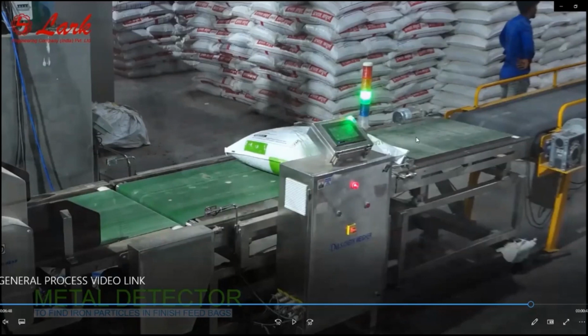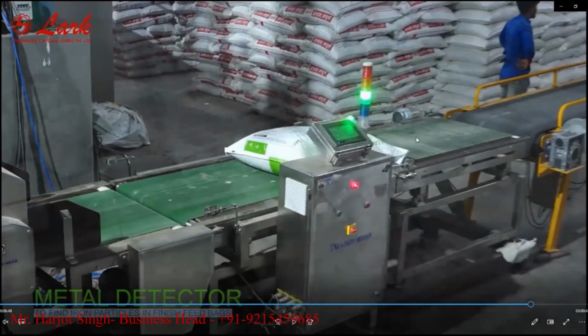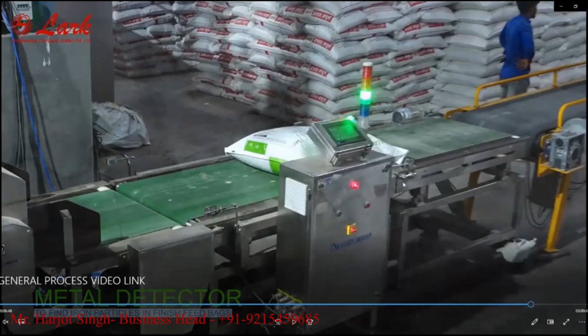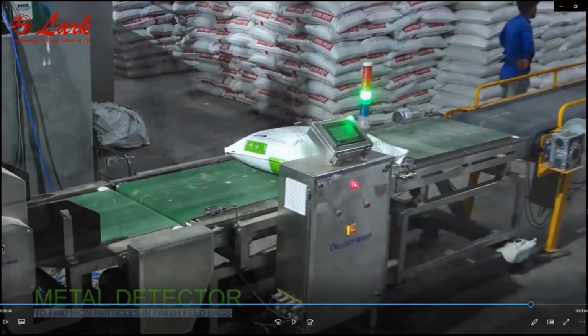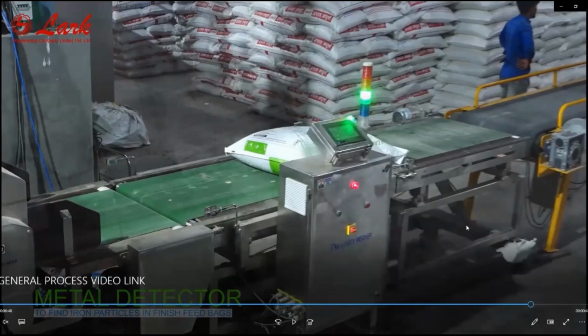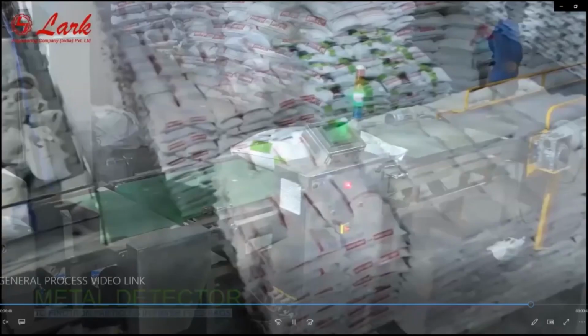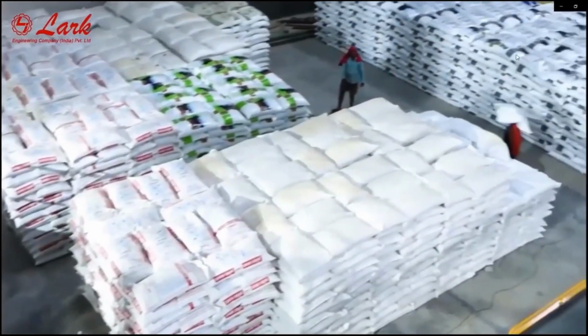If the desired weight is not within the tolerance of the set weight, this automatically stops the conveyor, and this platform is having pneumatic cylinders. Cylinders will open and this conveyor will tilt up and push the bag to the side, so that we can check the bag. So this is a very important thing in the auto bagging that we can add in our existing machines, feed mill also. So this is the complete idea of a feed mill process.